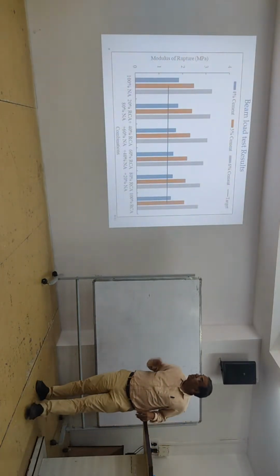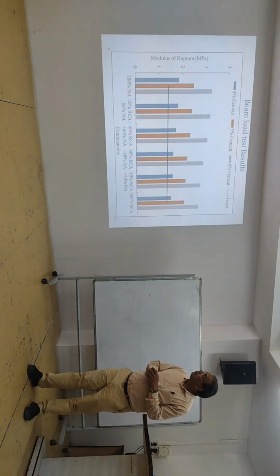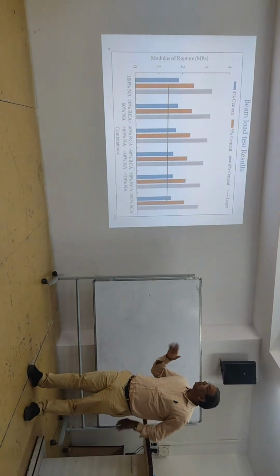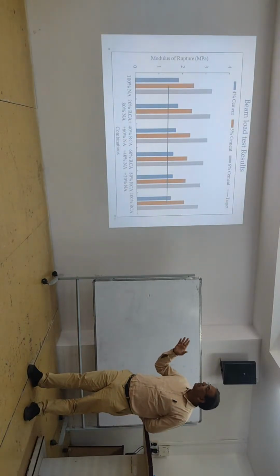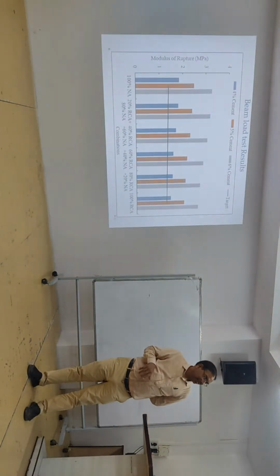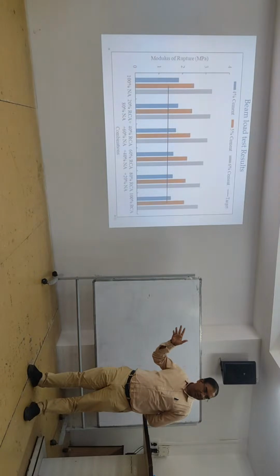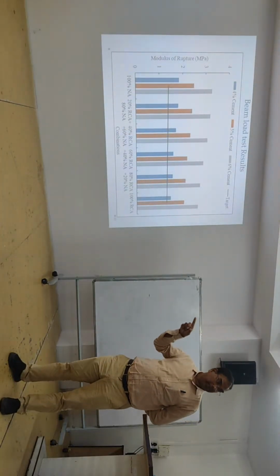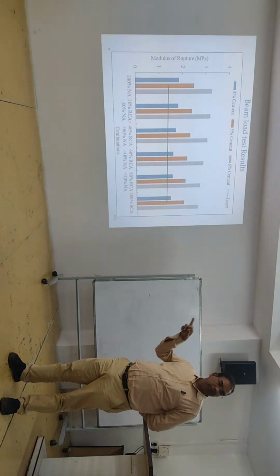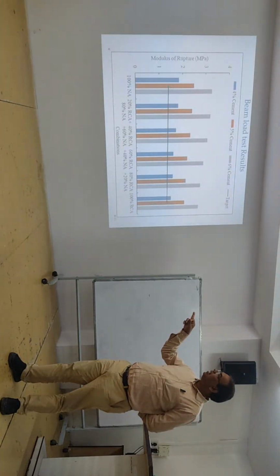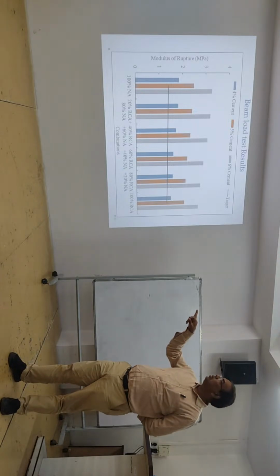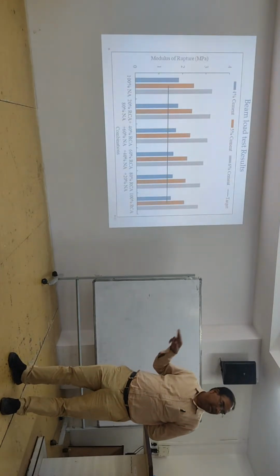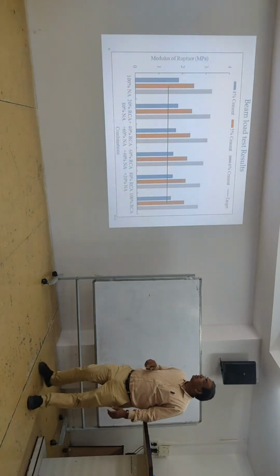So the beam load test, modulus of rupture: you can see that the minimum we are getting here is 1.5. This is for village roads. We have made the village road. For a highway we need 4.5, for concrete. So concrete needs 4.5, but here for village roads, for sub base and base, we require 1.5 around the target, and that we are also getting.